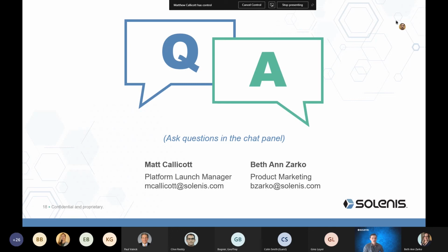So Clive's question is, any idea what percentage of softwood reduction was achieved during the furnish optimization? Sure. This is still being developed with St. Croix, but through some of our initial trials, we're seeing between 3 and 5% overall. Sometimes it would add softwood, sometimes we had significantly less softwood. What the system is really good at is providing the correct amount of softwood, or whatever lever we're looking to optimize at that time. So as the process shifts and moves, so does the usage. But overall, for the trials that we've run, it would average 3 to 5%, I would say.